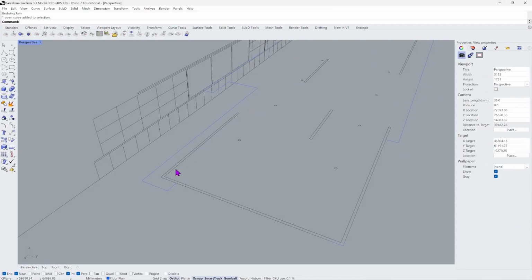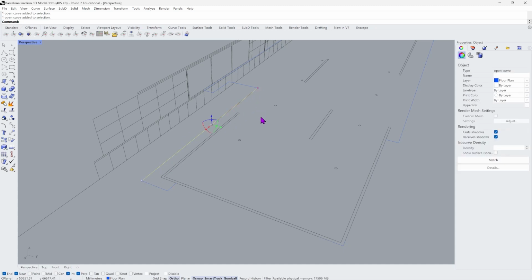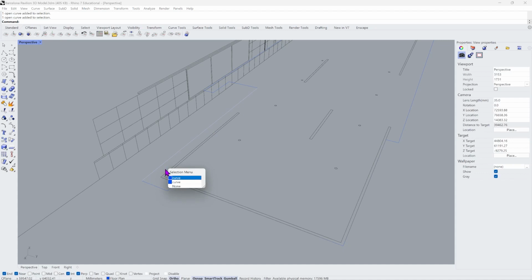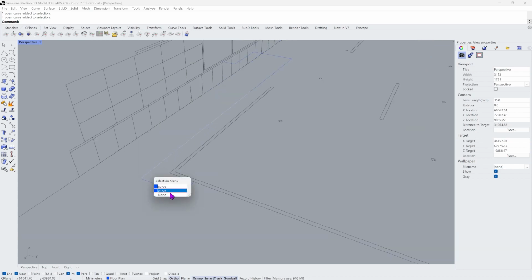With extrusion, if you have a couple of curves that are duplicating or overlapping each other, like for example here, it looks like a single curve going on here, but if you actually select one on opposite ends, you can see that there are actually two curves that are located exactly in the same place, that without any notes can be joined together and will create problem with extrusion later on.